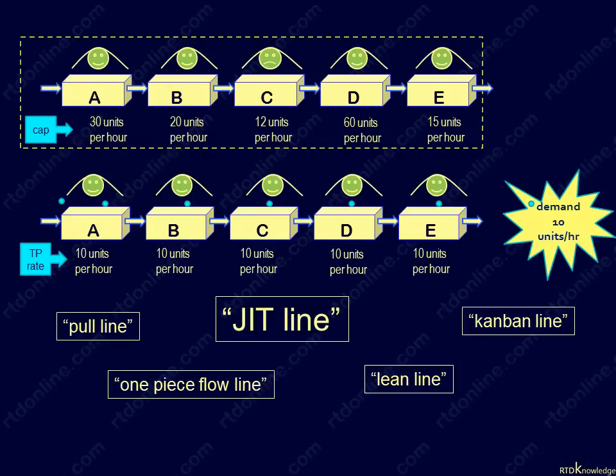Why call it a Kanban system? The Japanese term Kanban means a signboard. In a just-in-time line, it refers to the physical or electronic signal a station sends to its prior station, which tells it to start producing or delivering the next unit. The Kanban is a sort of internal purchase order one receives from its internal customer. The Kanban effectively controls the process flow in a just-in-time line and ensures every station works according to takt or the requirements of its next process.